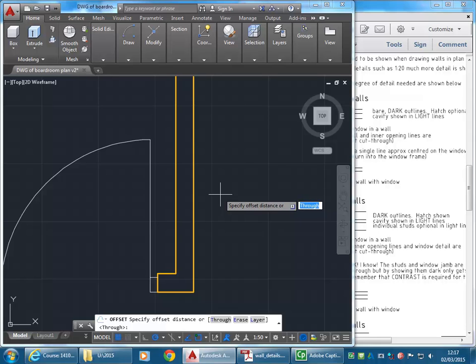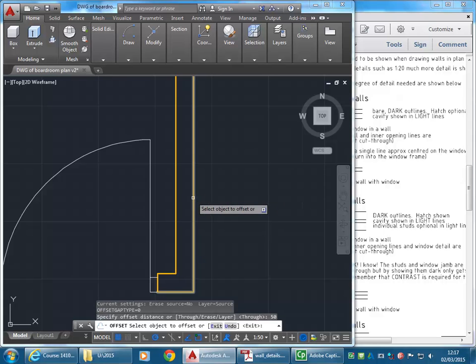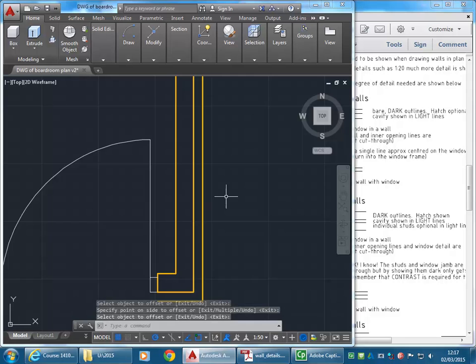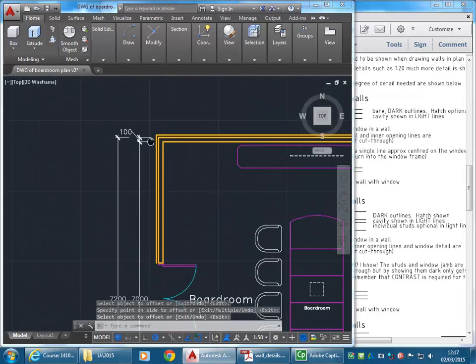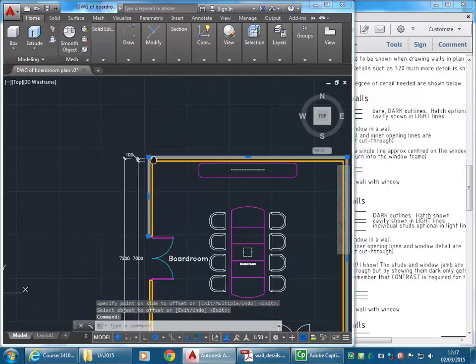So that's the bit of the wall, and then on top of that, on the interior side and the exterior side, you have like a lining. Yeah, you will. In reality, the stud framing won't be 100, so you can reduce the studs if you like. So that's up to you. But definitely a cavity should be 50, so I'm going to offset 50 mil there to the outside to make my brick wall, and I'm only going to take it up to here.